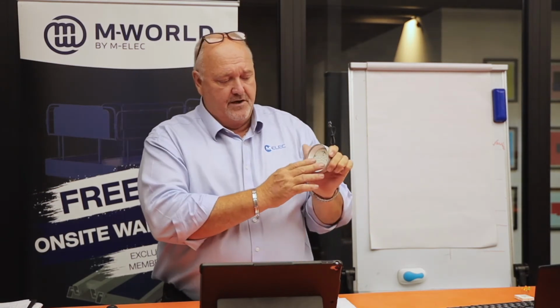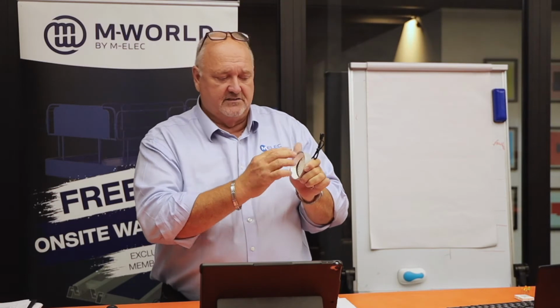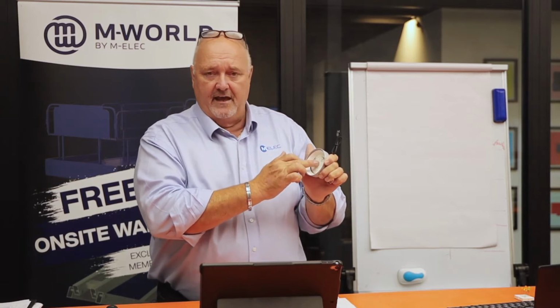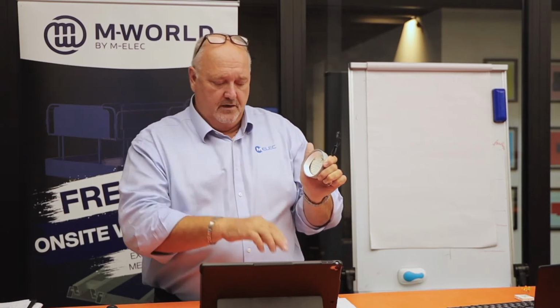Now the reason for that is I have a piece of reflective material that sits in there, but I have heat losses. Even though they're LEDs, I still have heat losses. Even though I've got this big heat sink, I still have heat losses. So the light there is going to be higher lumen output than the light, when I put it all back together, that I achieve here. Okay? Because the diffuser, the heat losses and everything else will take effect and cause the light to be different at that level. And that's why there's two levels.